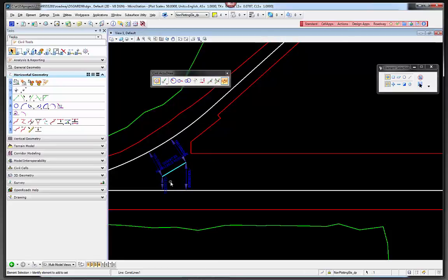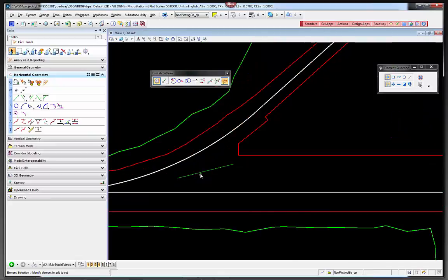So this is the fact that it allows you to persist, what's called persist rules on things that you build with civil geometry. And if you wanted to change something about it, you could change any one of these values here. Like, let's say instead of that being 100 feet off, it's only 50 feet off on that side. So now it's 50-50 over here and 100-100 over here, and it remembers the way you built the rules with that line.